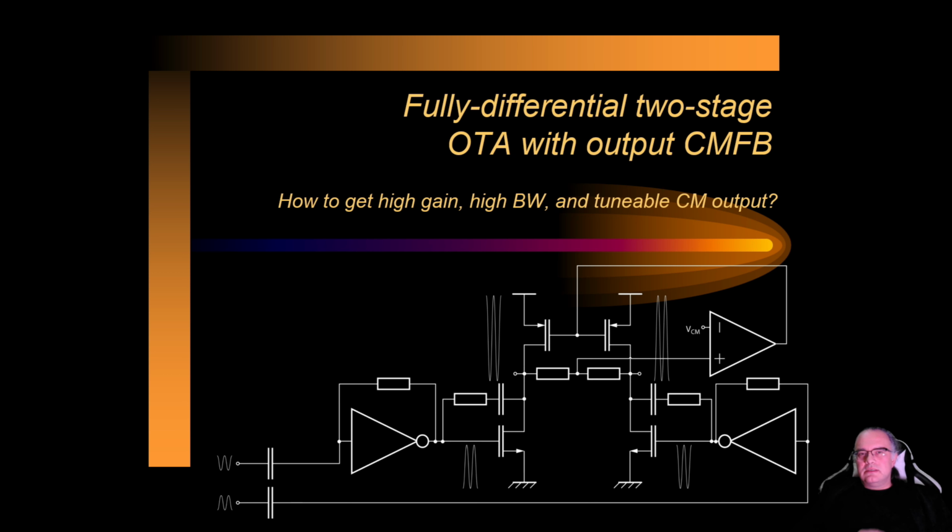So this is the architecture of a two-stage amplifier that I will discuss. The input is differential and AC coupled. The input comes from here, and then the first stage is composed of these pseudo-differential self-biased inverters. They amplify the signal somewhat, and they are also self-biased, so they operate in almost optimal operation mode.